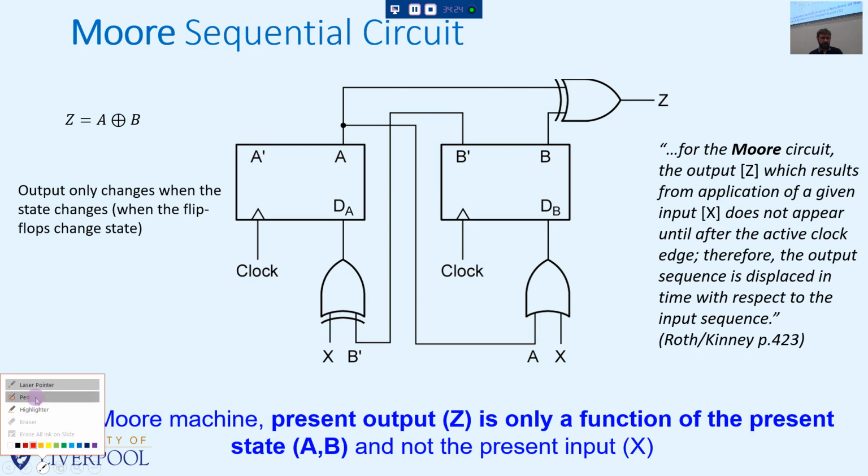And sometimes it can be helpful to even draw a dividing line across the middle of the flip-flops to show the divide between the present state and the next state. So here at the top, whereas it was on the right before, we have the present state. Here we have the next state of each flip-flop waiting to be loaded at the next tick of the clock to become the new state of that flip-flop. Okay, so state really now refers to the value of Q on each flip-flop.